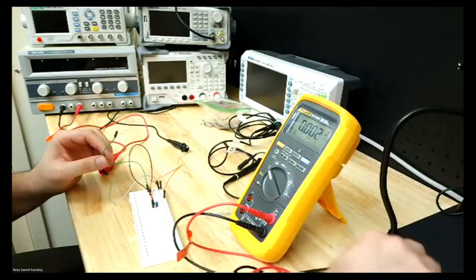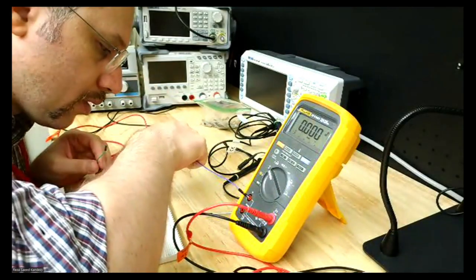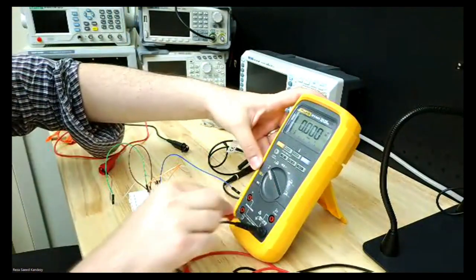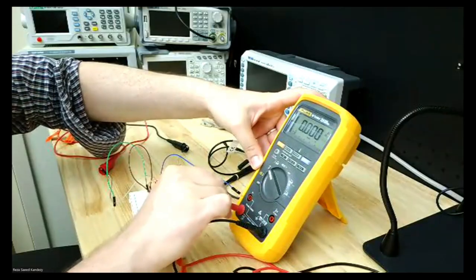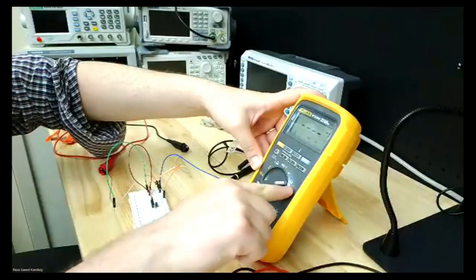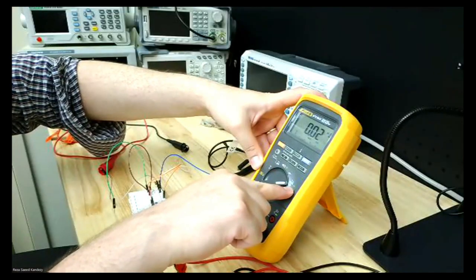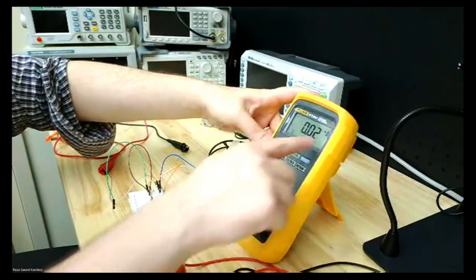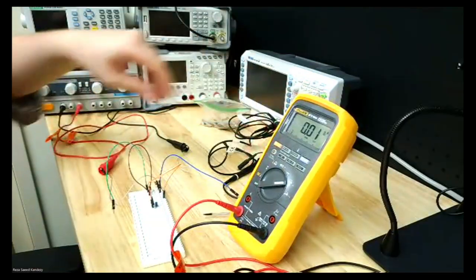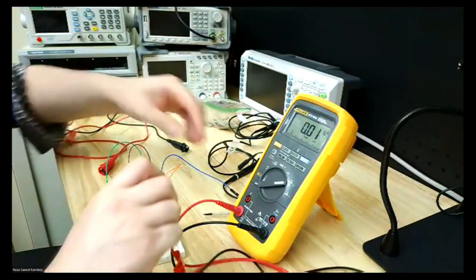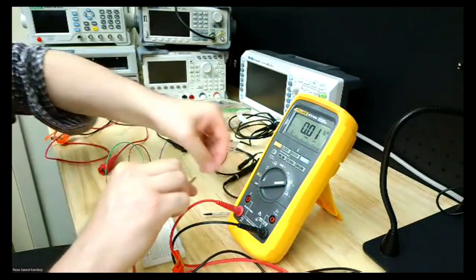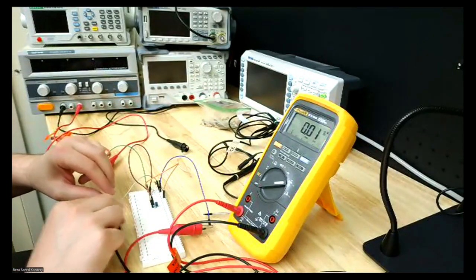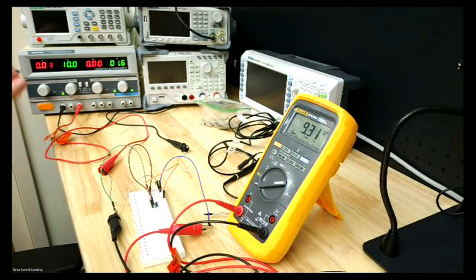So let me get a jumper cable. I'm expecting a milliamp, so I'm going to put this probe at milliamp and set the multimeter to milliamp. The value is still AC, so be careful, I'm going to change it to DC. Now I am going to connect my ammeter in series with my resistor and try to apply the voltage.